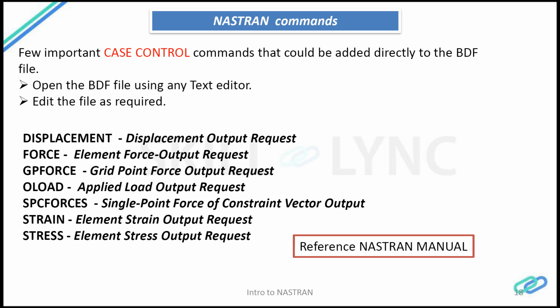SPCFORCES is the constraint force, or the end reaction forces for the boundary conditions. STRESS is the element stress, and STRAIN is the element strain. These are some of the important commands that you will be seeing in a case control section.